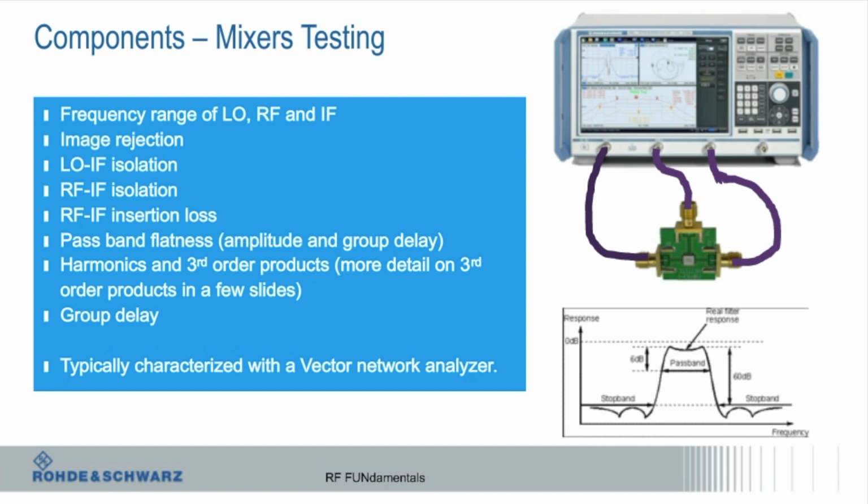So insertion loss, passband flatness, harmonics. I mentioned harmonics, so you're going to get integer multiples of everything. When you look at the output of a mixer, you see lots of stuff. It's not fun. Often when you design a system, you take a mixer, put some stuff before and after it, then put another mixer in. I did a system that had 3 mixers. There are filters in between, but stuff still leaks through at some level. So you've got to plan your frequencies very carefully.